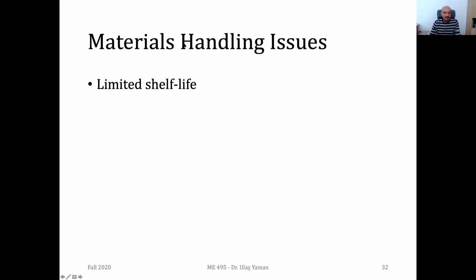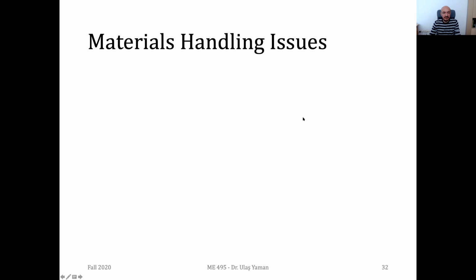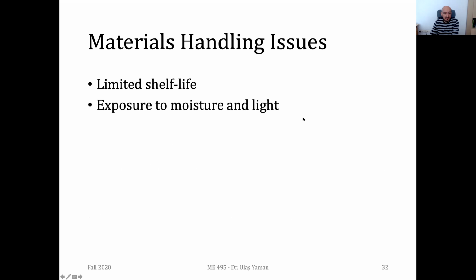As I mentioned, materials usually are prone to humidity, so they have limited shelf life, and you shouldn't have more moisture in the environment. You shouldn't expose them to light, especially if you use photopolymer material. If it's under, let's say, sun, then you may be photopolymerizing or curing the photopolymer.